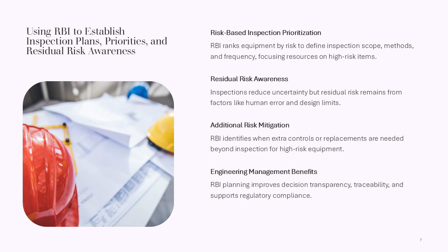This prioritization ensures that limited inspection and engineering resources are aligned with actual risk exposure. Inspection planning through RBI also supports broader risk management by clarifying the limitations of inspection. Inspections reduce uncertainty by providing data on equipment condition, but they do not directly eliminate risk.